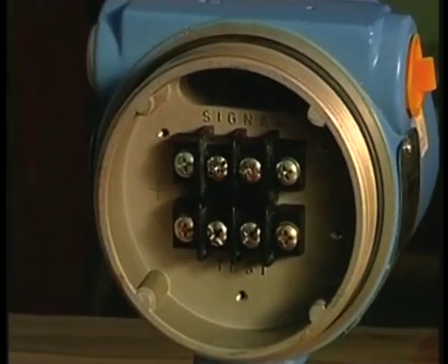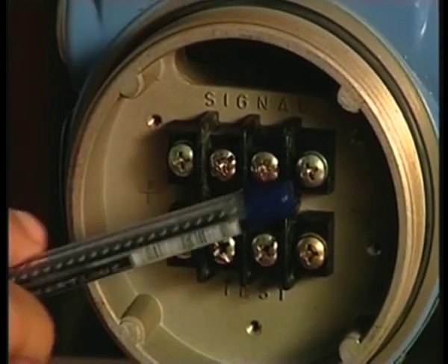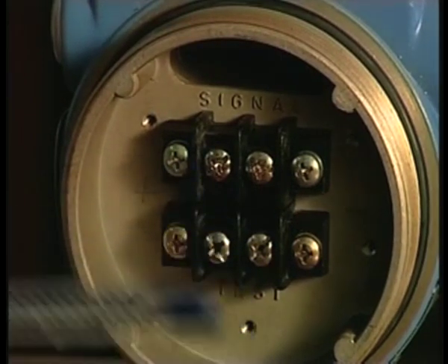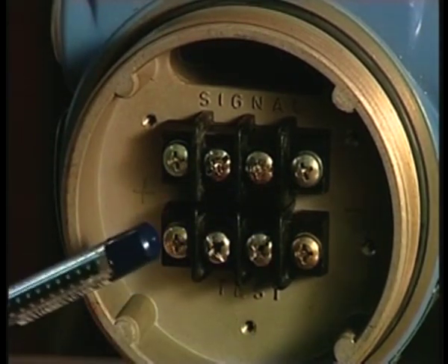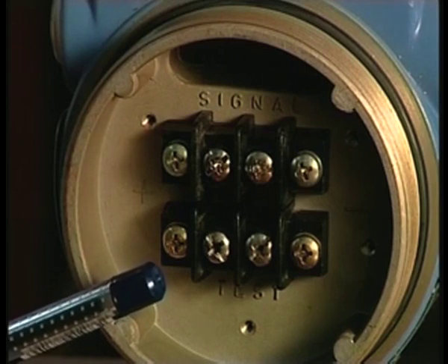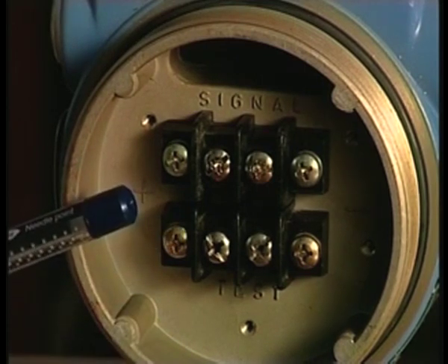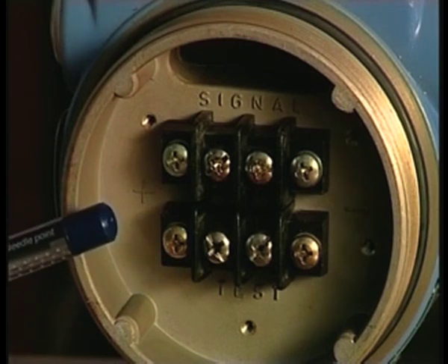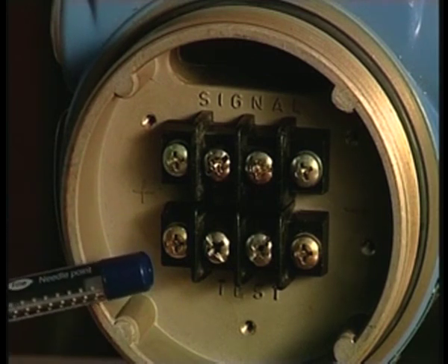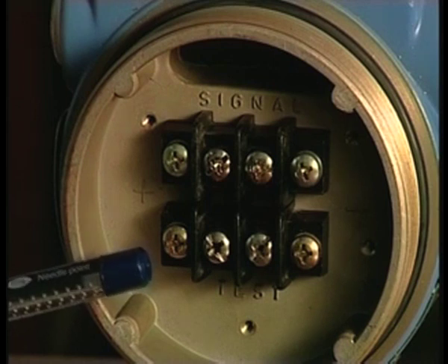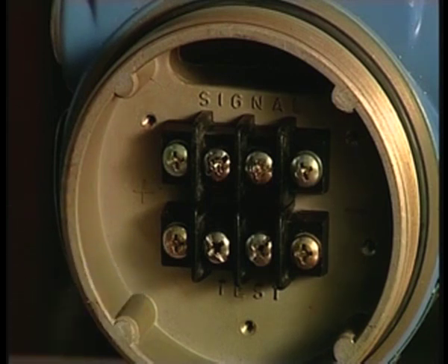You see we have positive signals, because in the process the output is 4 to 20 milliampere and the supply voltage maximum is 45 volt DC, because in all processes you cannot give a much higher supply voltage. That is also not necessary.